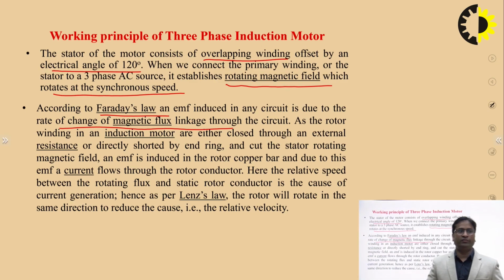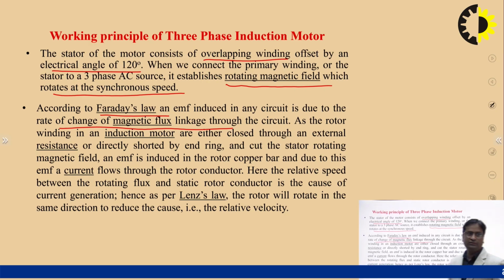According to Faraday's law, the EMF induced in any circuit is due to the rate of change of magnetic flux through the circuit. As the rotor winding on the rotor side is short circuited, there will be a flow of current, and when a current carrying conductor is placed in a magnetic field, it will experience a force. This is the law. So, your rotor gets started and it will rotate. This is the basic principle of the three-phase induction motor.